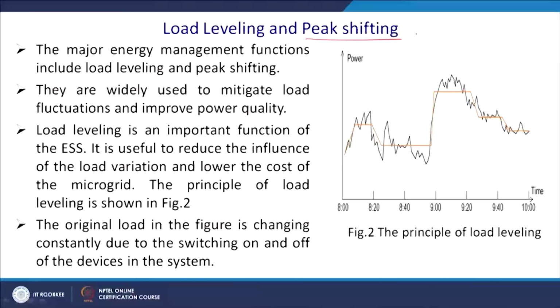Another important aspect in the microgrid that helps us to shape up our pattern of consumption is load leveling and peak shifting. In India we generally have two peak loads, but it is an oversimplified picture, and we have seen that for a duration of 24 hours we can have a plot. We have a peak load demand generally from 8 to 10 am in the morning, and from 6 to 9 pm in the evening.